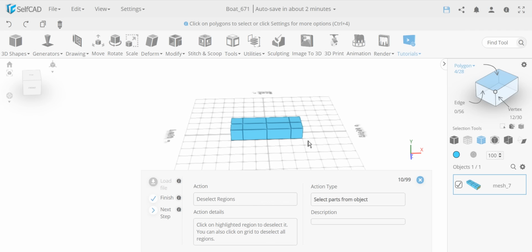You could have done this and added more segments. Instead of having only 2 segments, we now have 4 segments. We could have made it in 4 segments. But if you would have done it that way, you would later need to scale this down because these are not the same size. The segments you add in the cube are always the same size. This is a different size. So there are actually 2 ways to do something like this. You can create them bigger and then scale it down, or the way it's done now, where you just later extrude.